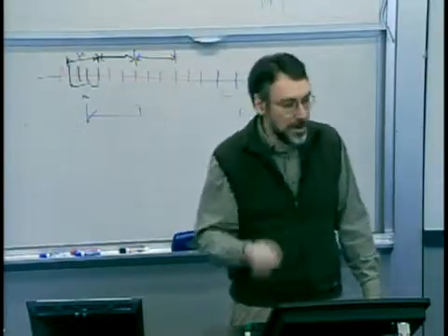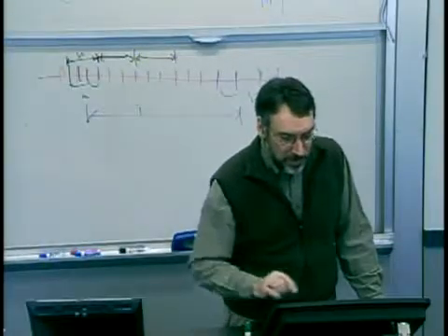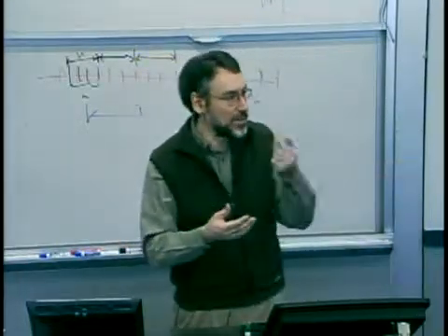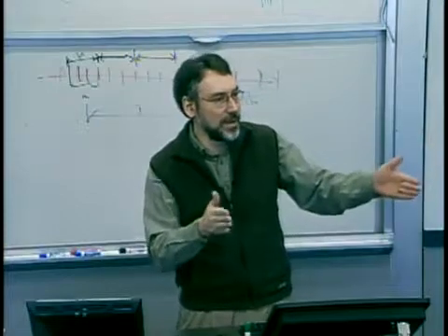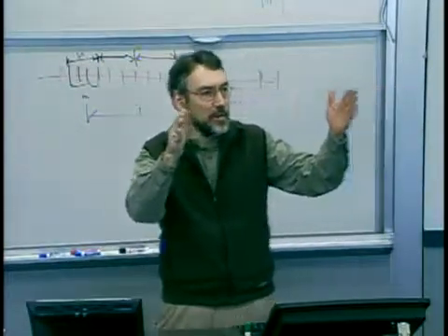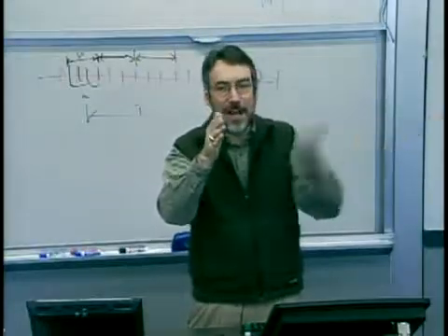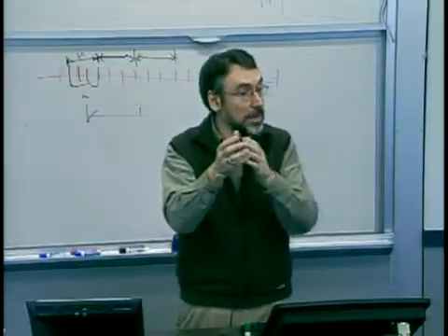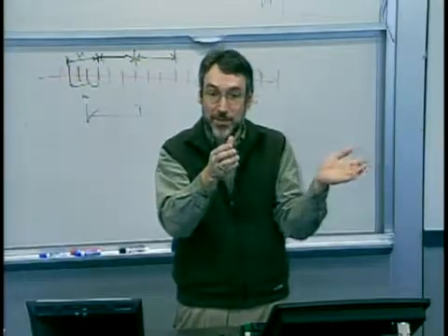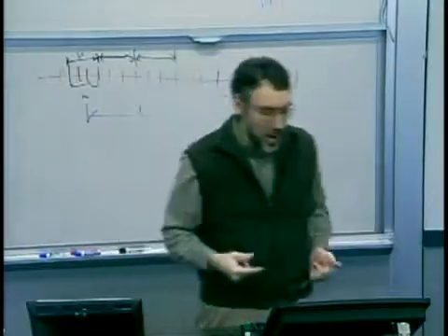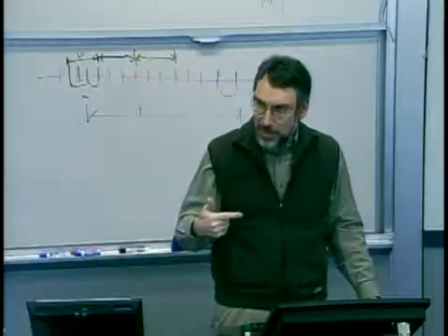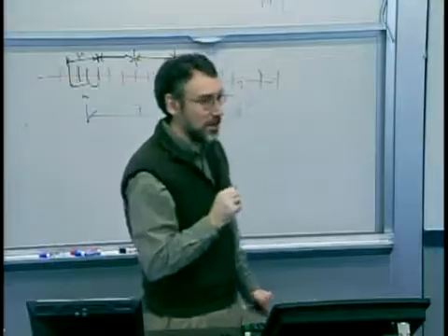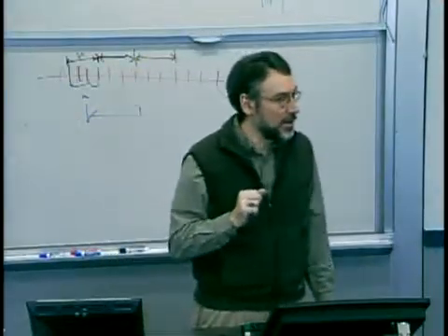So an approach here is to use a variant referred to as a running control chart or a running average. You look back not just on the new sample, but some number of previous data points, and have a window that moves along or some calculated average of past history where I might weight my most recent measurement either equally or more heavily than my past measurements, and use that as an estimate for the process average and the process variance. Does that violate the independence assumption? Absolutely. It does violate the independence assumption.